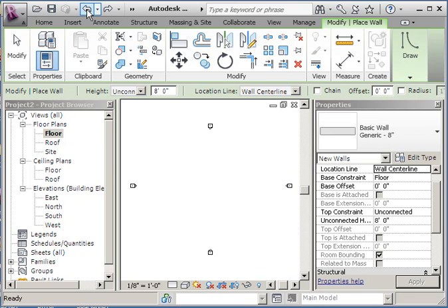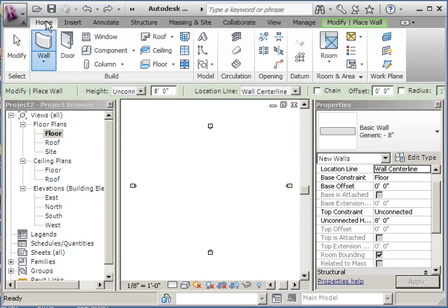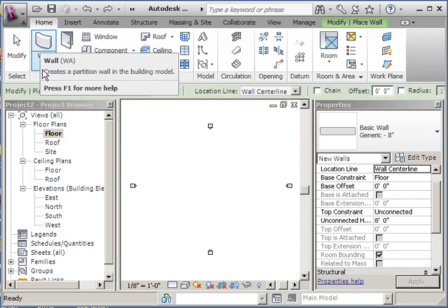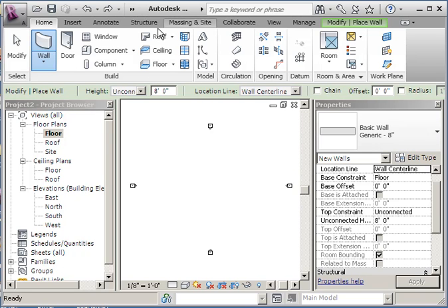And then it says under the Home tab, select Wall in the Build panel. So if I go back to the Home and click Wall, see, this is the panel. These are all panels, and that said Build Panel. So you look right here for that. And once you click on Wall, it says choose the rectangle in the Draw panel. So you want the rectangle to show up.